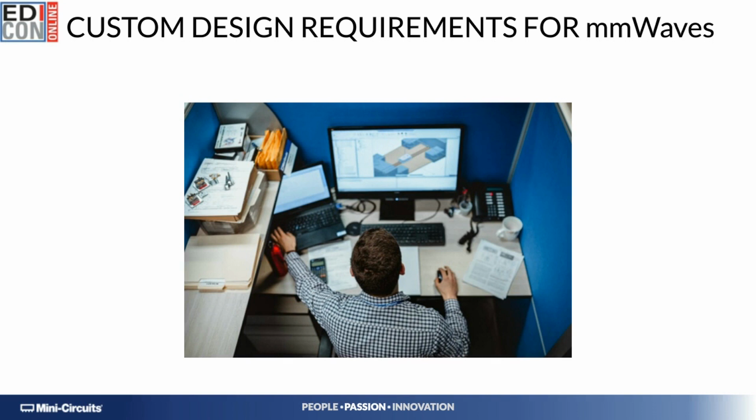Designs such as bandpass filters are varied from application to application on center, cutoff, and stop and rejection frequencies, as well as levels of insertion loss, return loss, and so on. When you cater more than 20,000 customers, as we do here at Mini-Circuits, believe me, there are many flavors to a bandpass filter request centered at the same frequency. This greatly exacerbates at millimeter waves, since the percentage bandwidths translate into massive absolute bandwidths. So custom designs are the new norm at these frequencies.